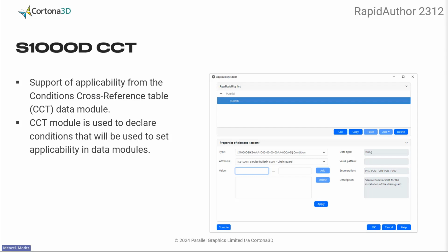The last authoring feature I'd like to briefly mention is an improvement to the S1000D authoring workflow, specifically to the way you use applicability. Applicability in S1000D decides on a very high level if something is applicable to a certain variant. Say, one configuration of a car has a heated windshield, another one doesn't. Based on the applicability setting of the windshield heating, related instructions in your documentation would be included or excluded.